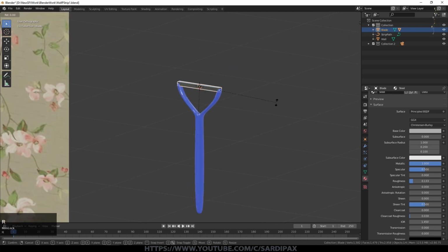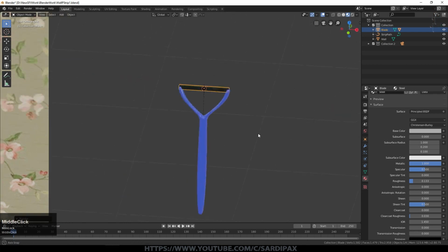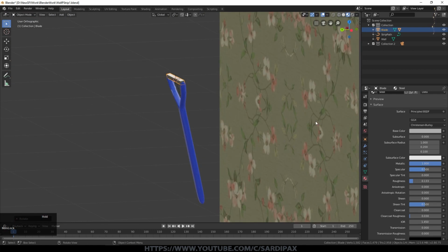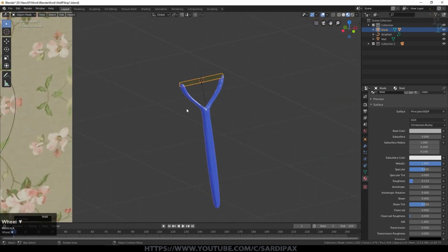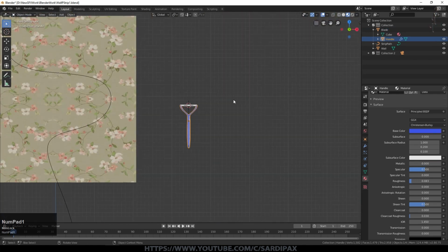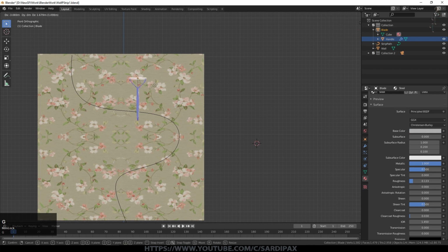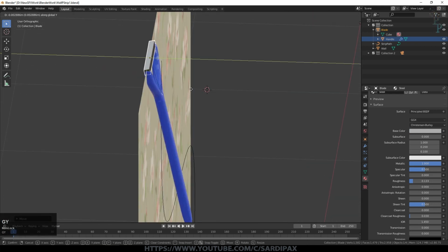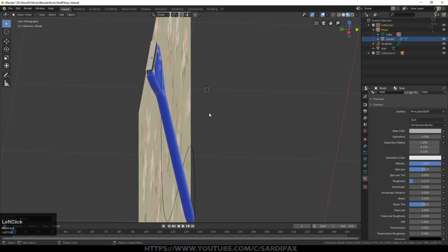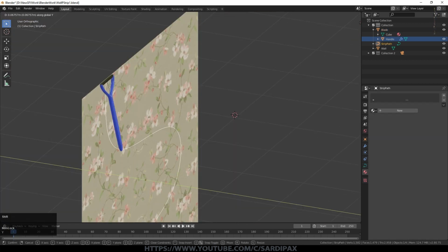And now I'm just going to rotate the blade on the X axis just to tilt everything out slightly there, like that. Obviously you can put a bit more work into the blade to make it a more realistic blade. So that's our tool. And what we now want is for this to move along that path. So selecting the blade, let's move that over to about here, the starting point. And we want it to just impinge with the wall surface very slightly. And I'm just going to move that curve in slightly so it's about level.